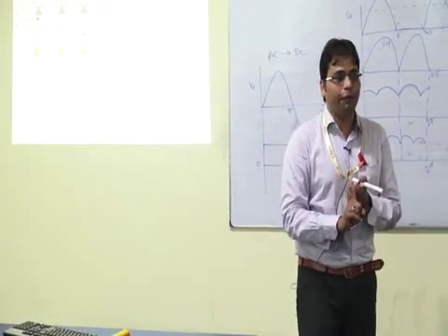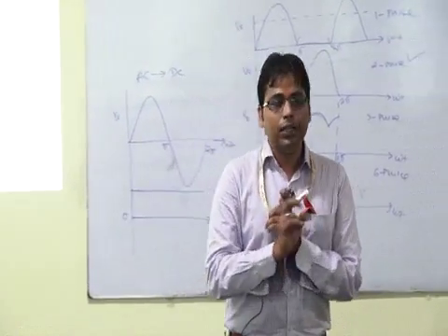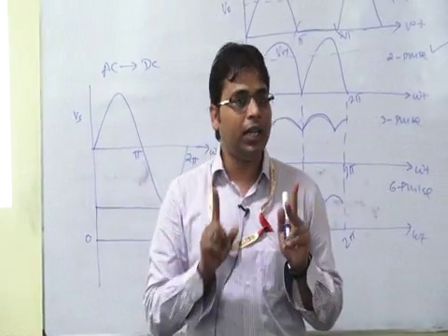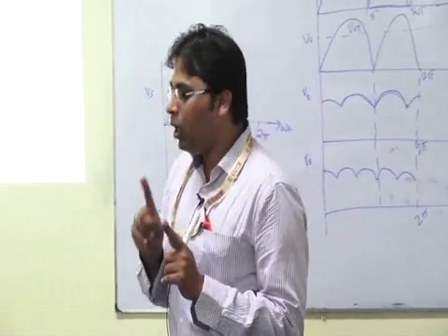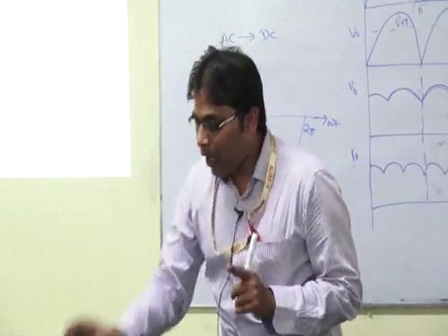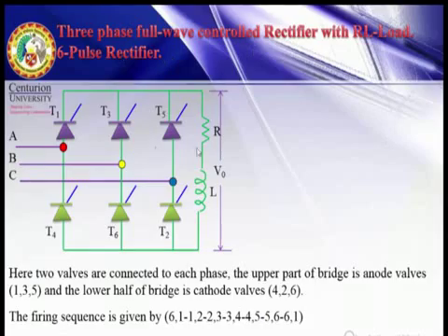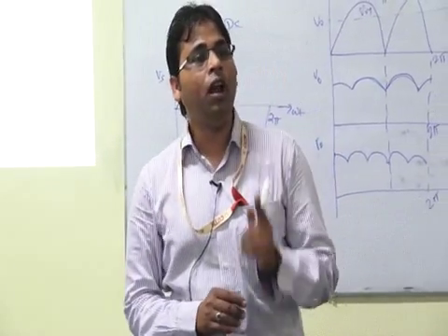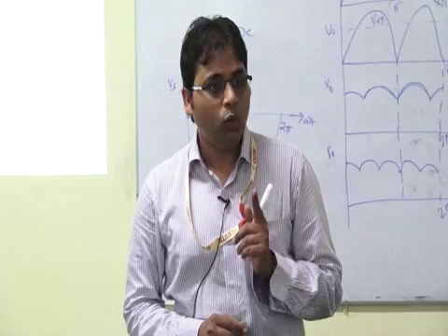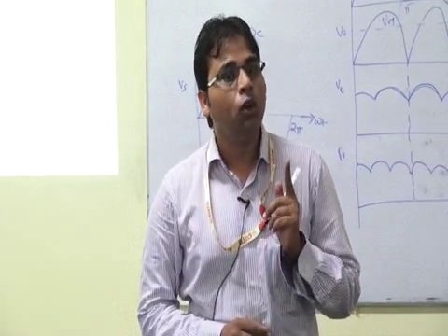Before going to the waveform, first remember that 2 thyristors will conduct at a time, one from the upper half and another from the lower half. One thyristor will conduct for 120 degree.